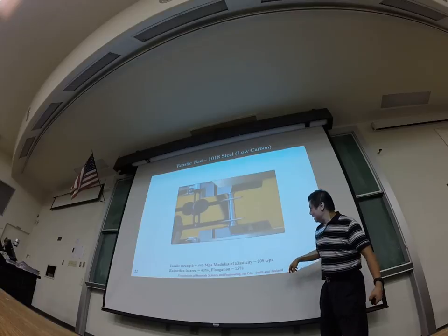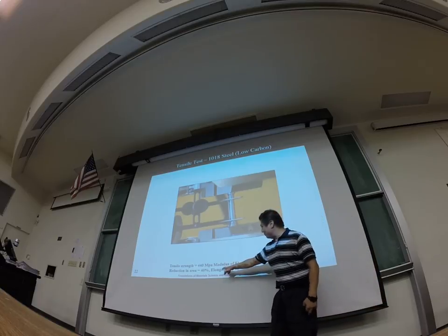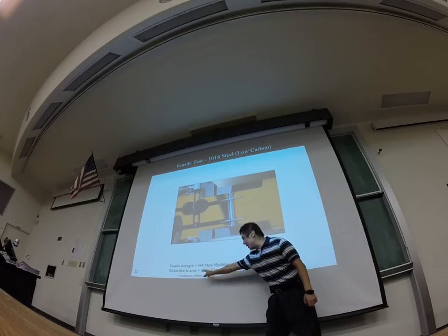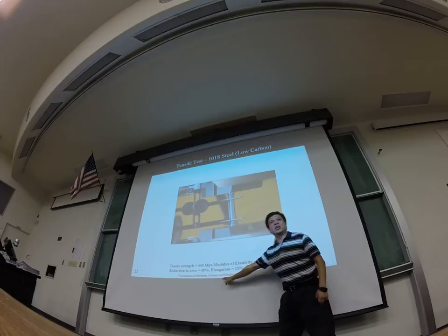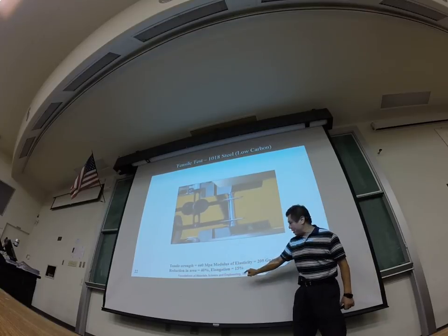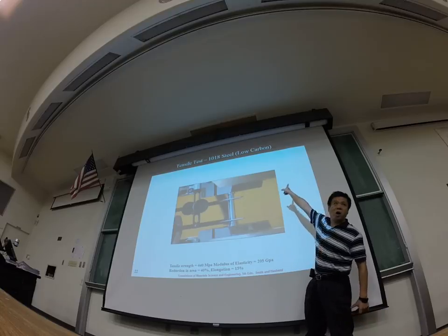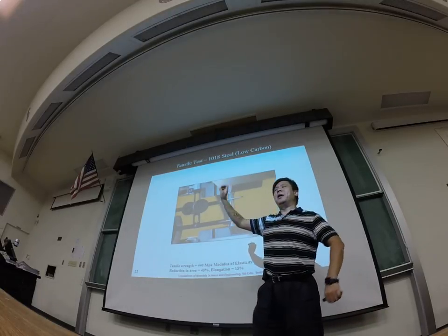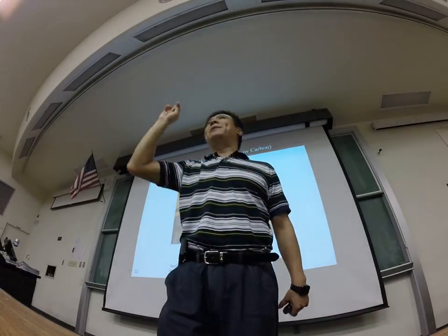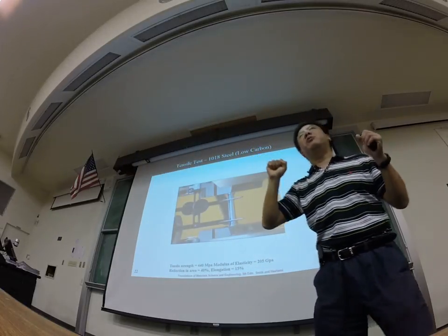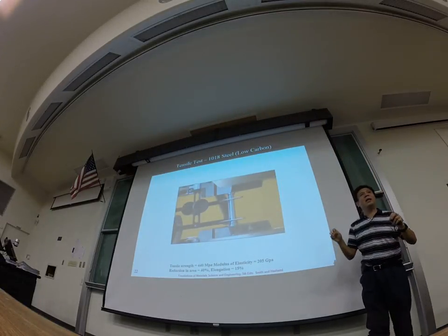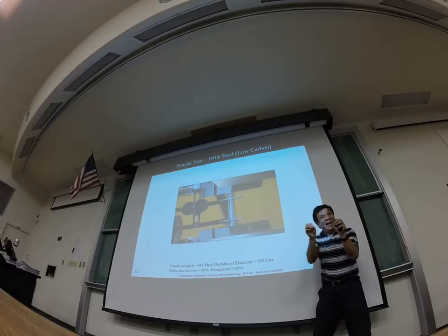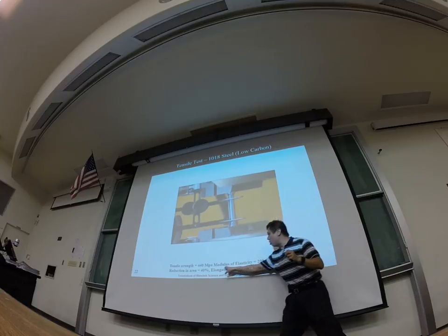But anyhow, this also gives a reduction in area. You need to know what that means, and the percentage elongation. For this low carbon sample, low carbon means the carbon dopant level inside is reasonably low. That usually leads to what? Less strength but longer elongation.